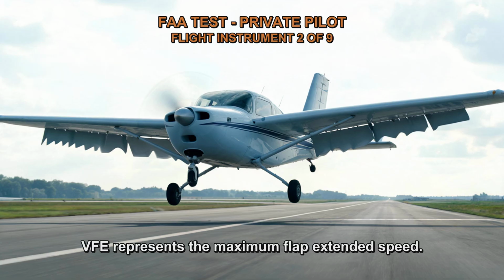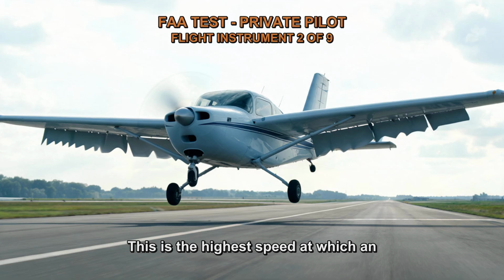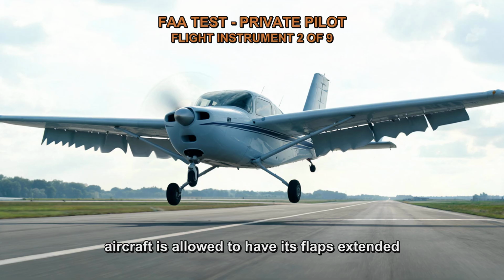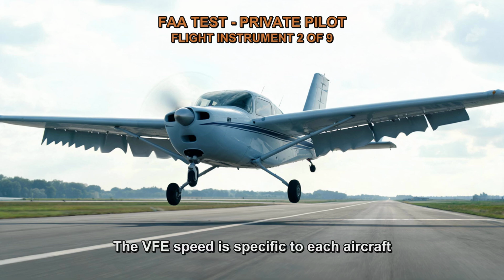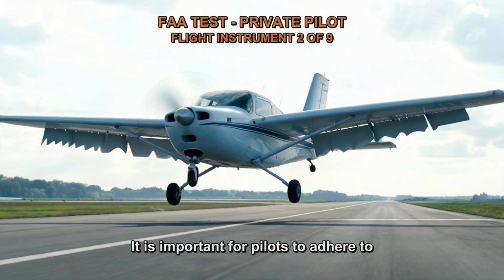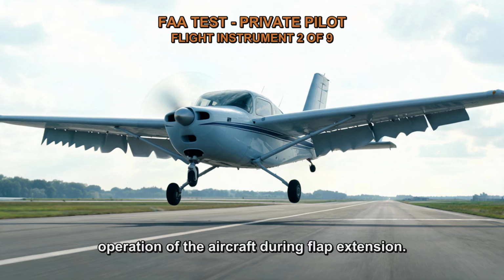VFE represents the maximum flap extended speed. This is the highest speed at which an aircraft is allowed to have its flaps extended without causing damage to the aircraft or compromising its structural integrity. The VFE speed is specific to each aircraft and is determined by the manufacturer. It is important for pilots to adhere to this speed limitation to ensure safe and proper operation of the aircraft during flap extension.